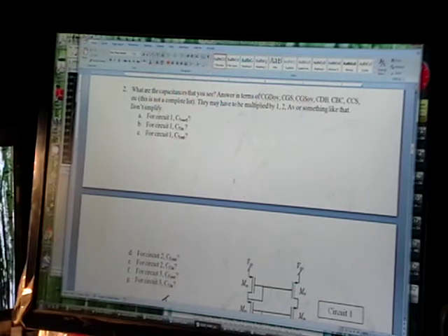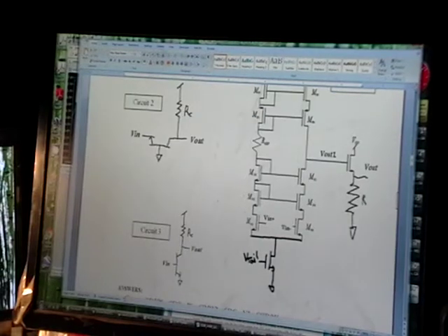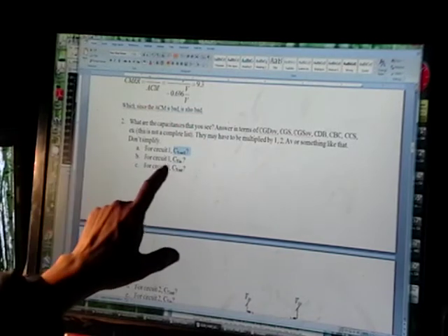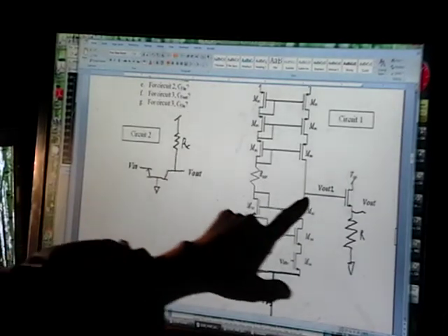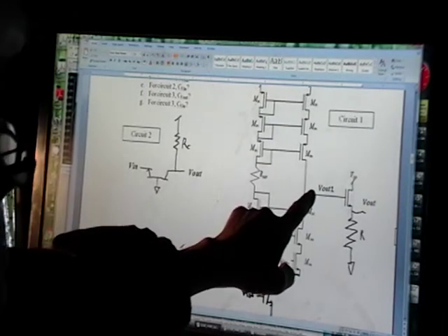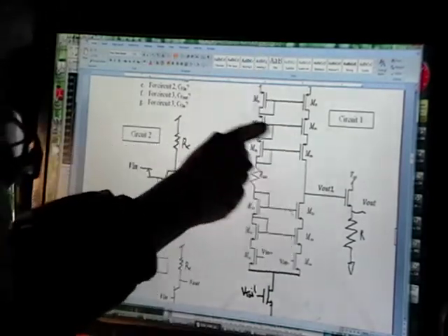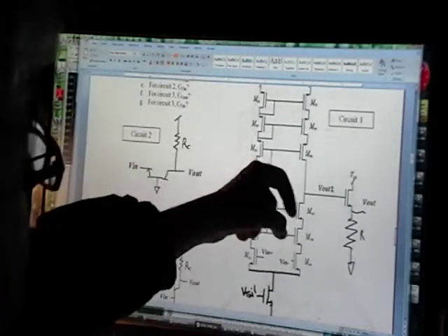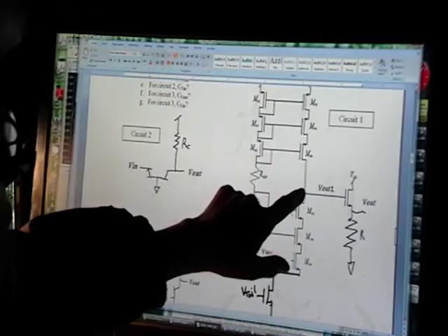Okay, so the most important part of this: these are the questions that we haven't practiced in class that I do want you to be responsible for on the final. So let's see what we're doing here. This is just finding capacitances at nodes. I gave you 3 circuits here, and the first question is, what is the capacitance at this node right here? What you have to remember is that if you're sitting on this node, you go in all directions on the wire, not just forward, not just backwards. You go all directions you can possibly go until you run into a transistor.